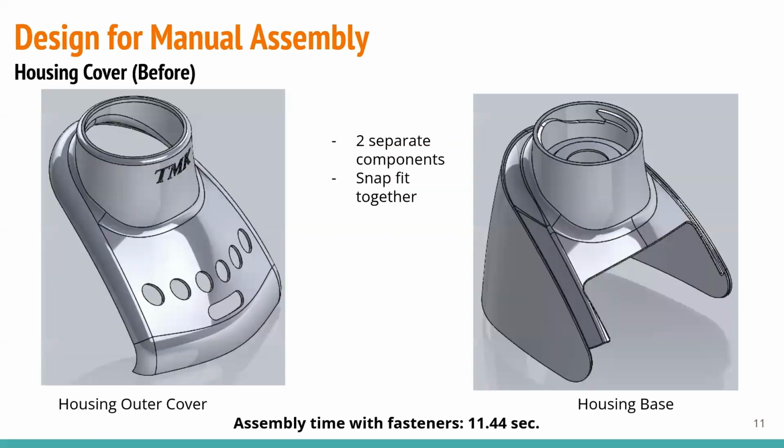We chose these two parts for DfA design because, according to the quad chart, both of these parts had a high functional importance but also a high cost, indicating they should be modified to decrease cost while maintaining the function of the blender. Additionally, the assembly times for each component were higher than other components, so there was the opportunity to decrease assembly time and costs.